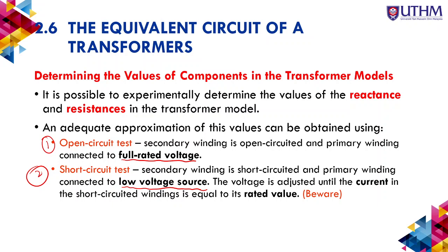That one is if you have a load. But for the short circuit test you must use a very low voltage, and then you adjust the current so that it becomes the rated value of the current.